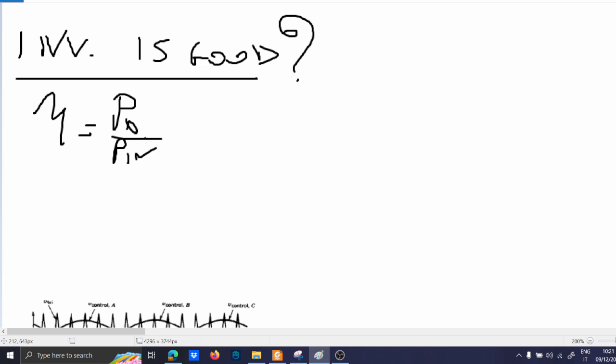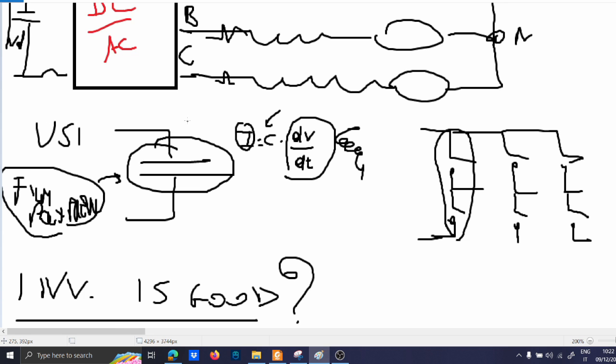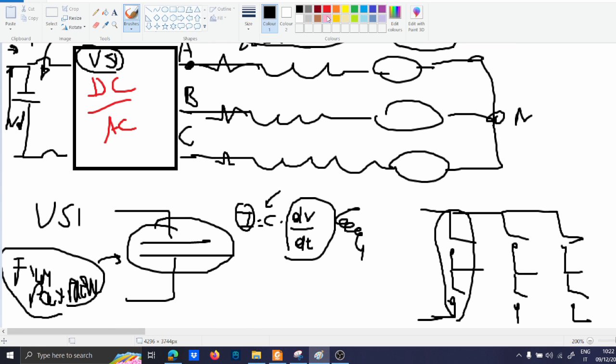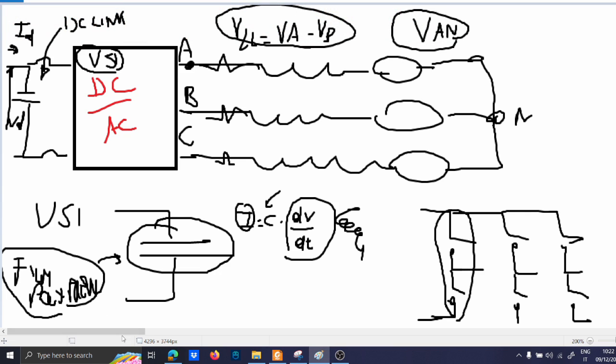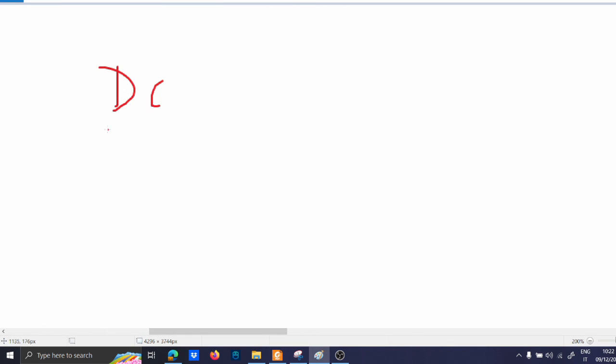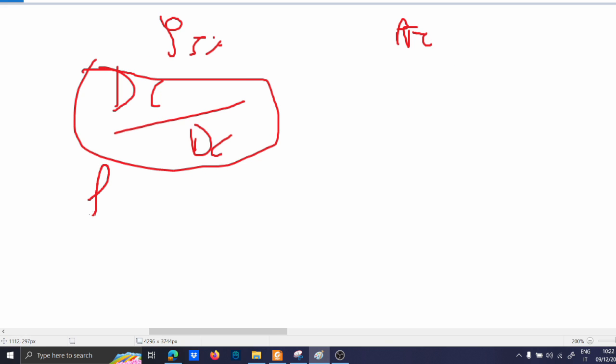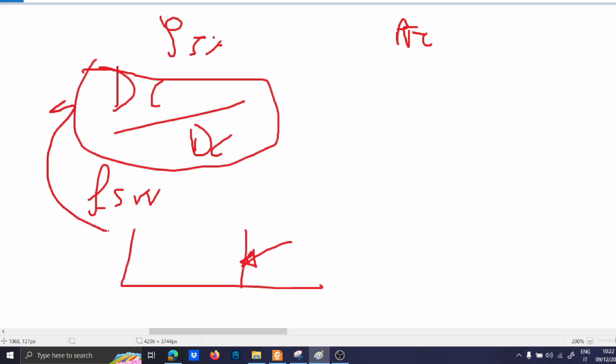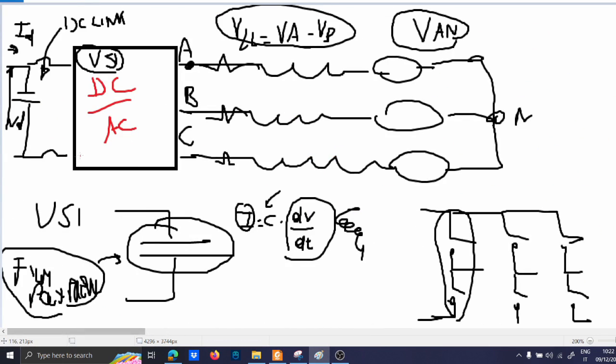But aside from the efficiency, you have in the inverter something very peculiar, which you don't have in the DC-DC converter. Let me remind you a bit. In DC-DC converters, 95% of the time, except the PFCs, you have just the switching frequency in the circuit, and in the spectra you expect the component of the switching frequency, both in the input and in the output, which have to be filtered, okay? But that's it. The inverter instead has something different.